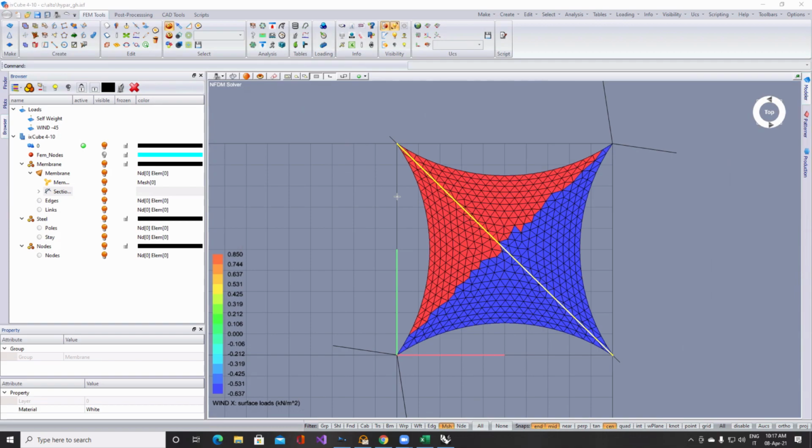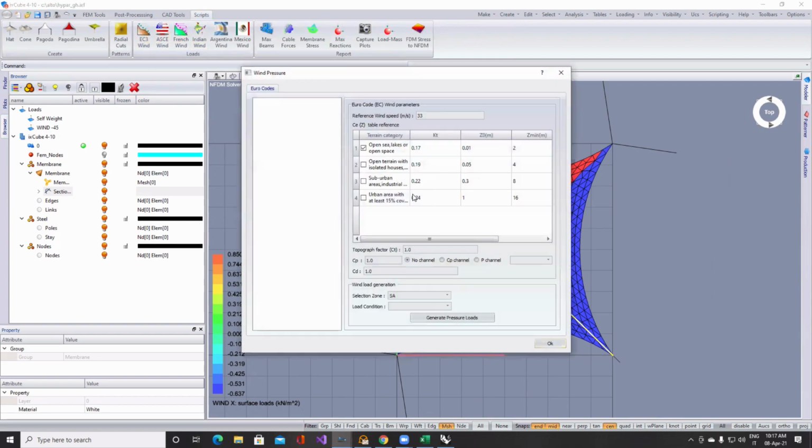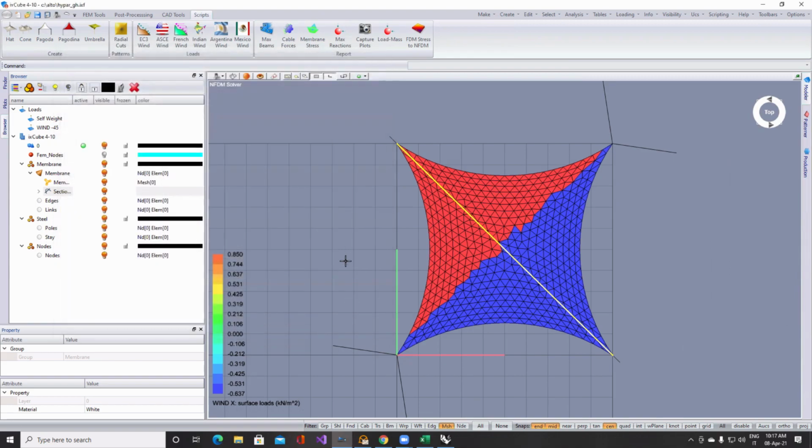Once we have done all this work, we come here, we select the areas, the zoning, A, B, C, whatever it is, and we input the values in this tool here to generate the pressure on the surface. So basically, the pressure on the surface, in this case, depends on the selection that I have made and on the CP values that we are using. Clearly, the height of the structure is evaluated in this formula, but what is important is the CP value. Is that clear?